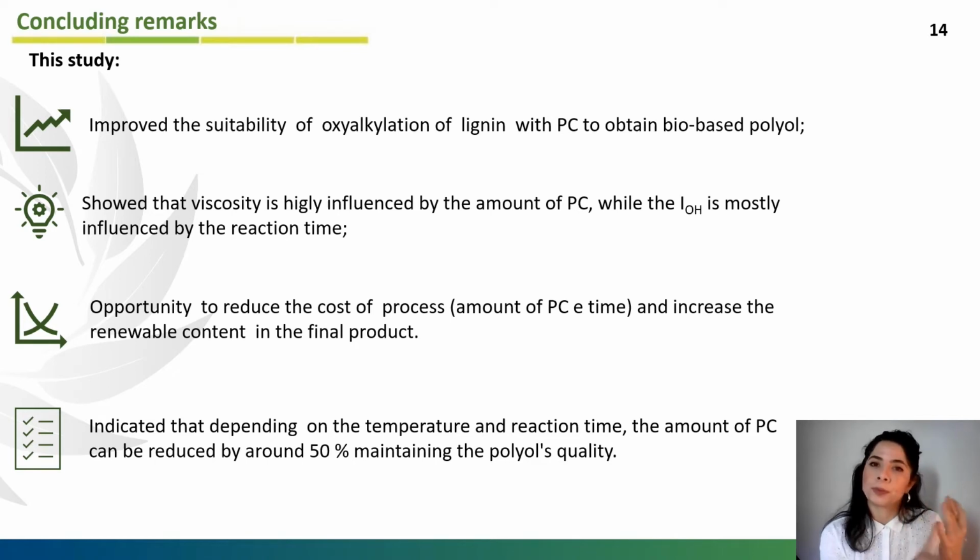Okay, so last one, the concluding remarks about this work. We can improve the process, the oxyalkylation of lignin, using a DOE, and also specifically for this work, you can see that the viscosity is highly influenced by PC amount, and hydroxyl number is the most influenced by reaction time. And also we reached our objective, it means we reduced the PC amount and also increased the renewable content in the final product.